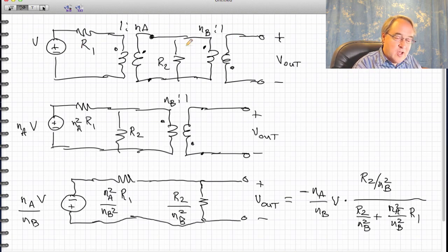So we've taken a fairly complex circuit and by manipulating it reduced it to something where we can just write the answer in the end. One other thing I would point out is that you do have to be a little bit careful in manipulating here. If we had wanted to solve for some other signal that's not at the output, like suppose we wanted to find this current right here, I'm going to call that IA. IA does not explicitly appear in this final circuit, and in fact when we push the elements through the transformers we have to be careful.